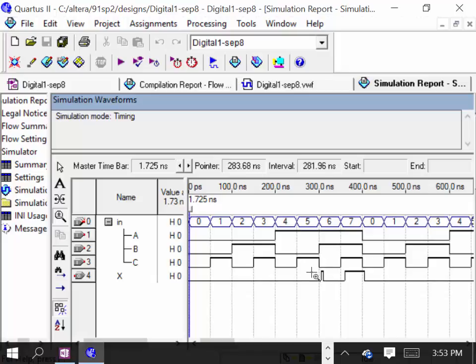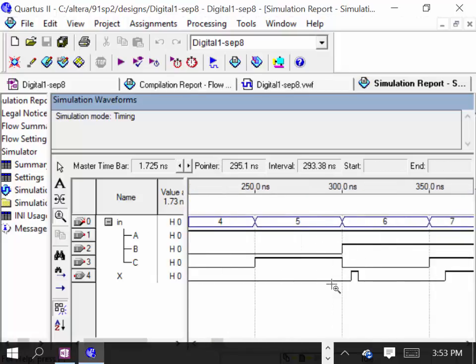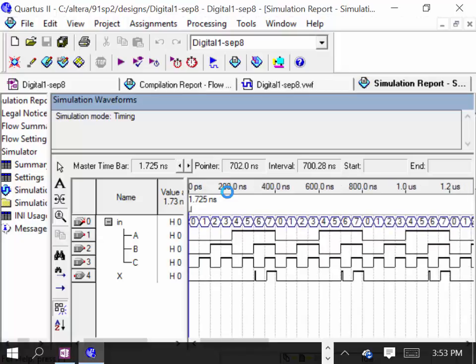As soon as this one goes low, is registered low inside the chip, then the output goes low. But because of the timing, right here this shows it as if it's happening at the same time, but in reality, inside the chip, it's not. So you get this little bit of a glitch right there, and it's going to show up every time.